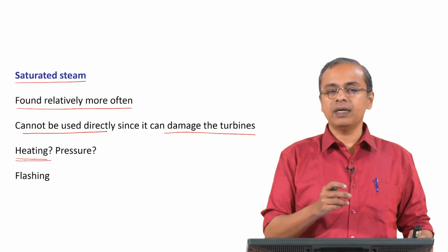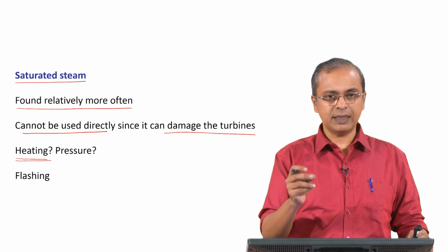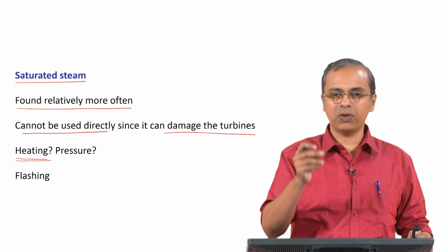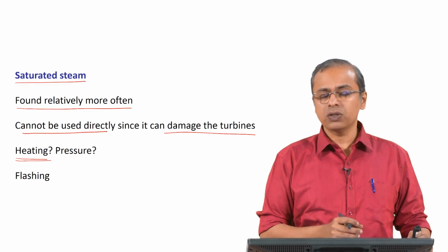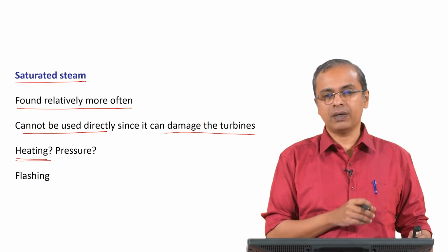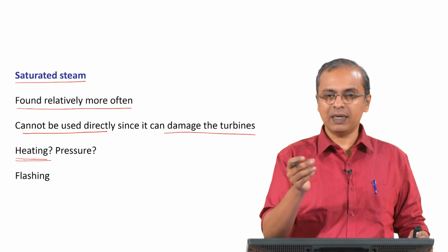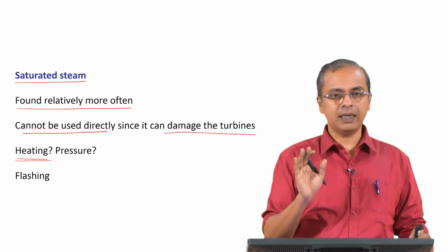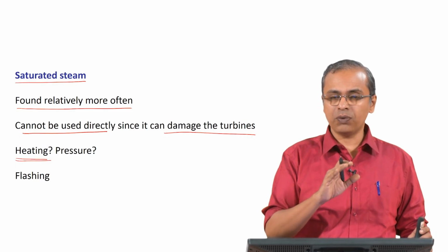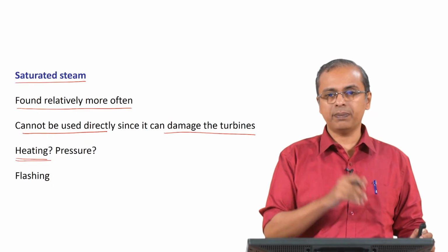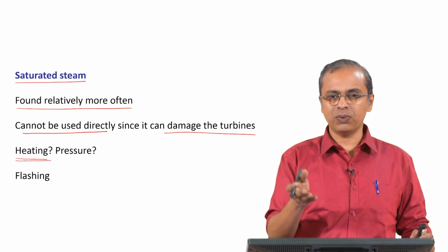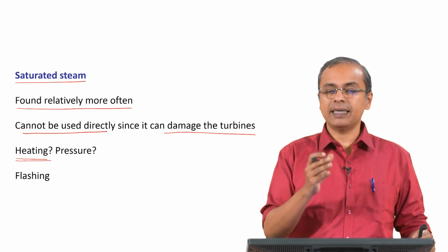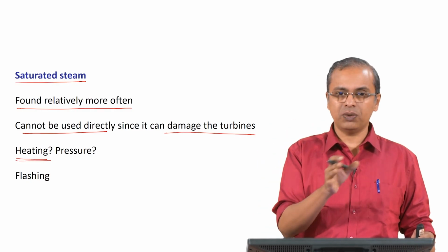Here you already have steam. It is just saturated steam, so you have already taken it to 100 degrees C, got it past the boiling point, and it is in steam form. So with relatively less coal, for example, if you had to use coal, you can get it to become superheated steam. You will not be 100% clean in that sense, because you are going to use some fuel, maybe coal, maybe oil, to do this final bit of heating to get it to become superheated, and then you can use the same turbine that you used before.